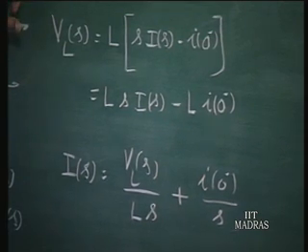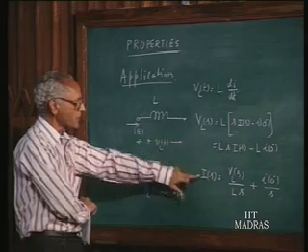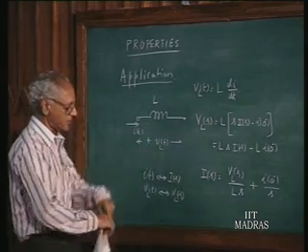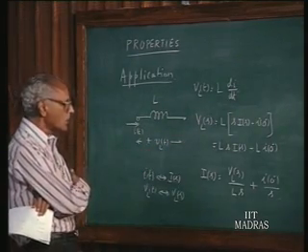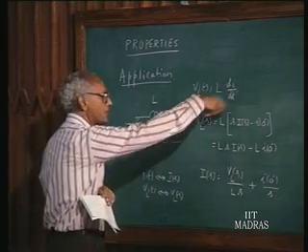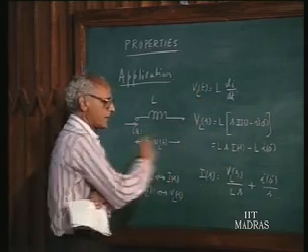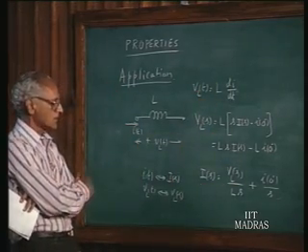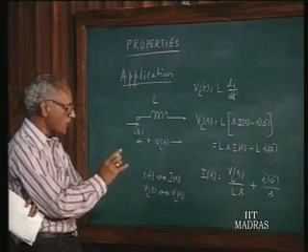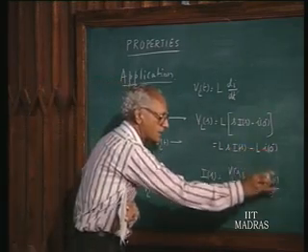This is the terminal equation of an inductor in the time domain. These are the equations in transform domain. Both are equivalent to each other. Notice one thing, that the derivative operator is removed. These are purely algebraic equations. However, the extra term that you need to have here is information about the initial conditions in the inductor.